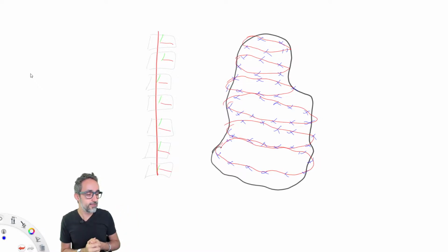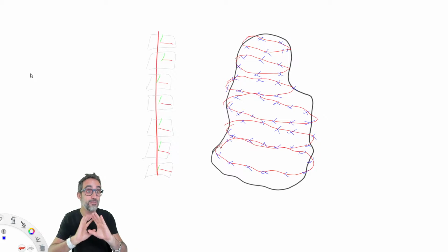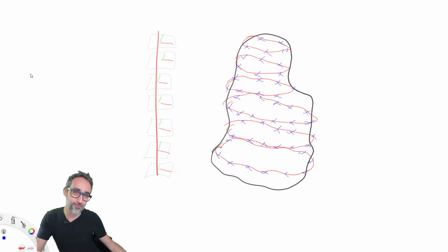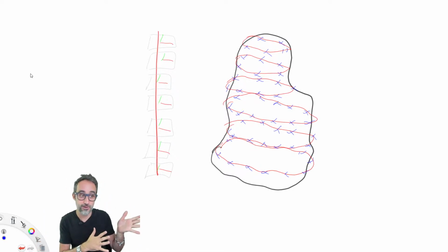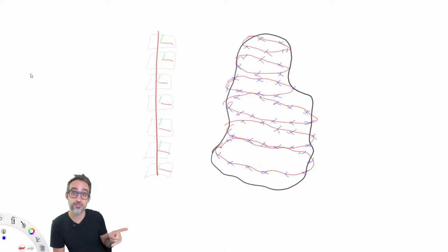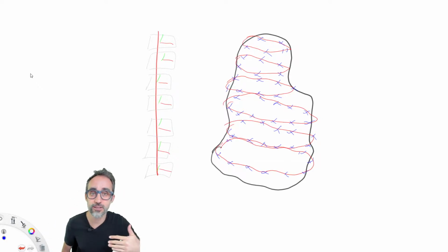Now, once we have all these contours and all this subdivision, for this exercise we're not going to bother about infill material, overhangs, or support material. All of that is the stuff that is actually difficult and is still undergoing a lot of research these days. We're not going to care about that. What we're going to care about is the last process, which is taking all of this information and turning it into some kind of textual representation that a machine can read.